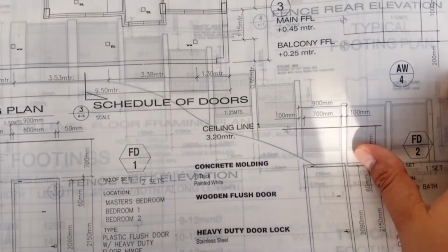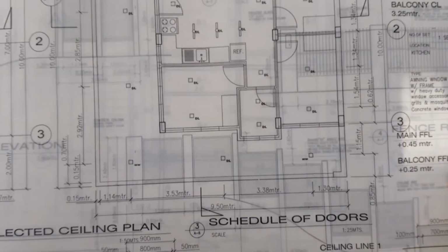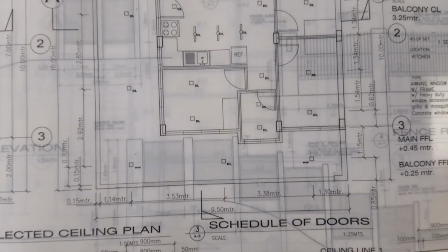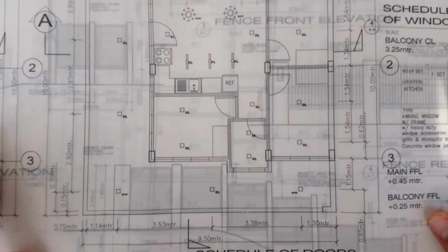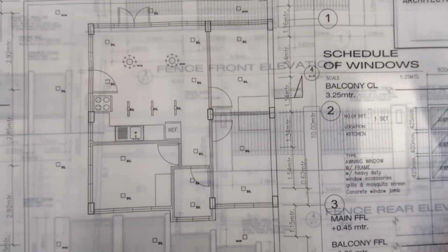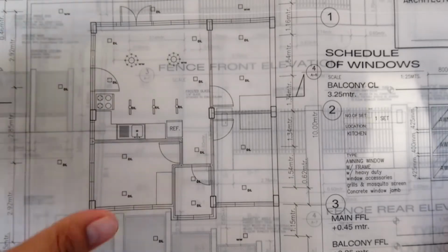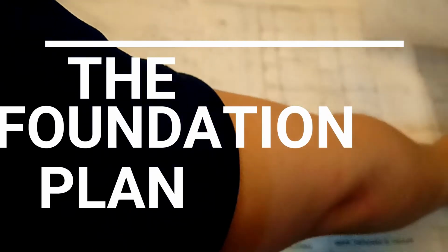I think our last assignment is for you to do the reflected ceiling plan. Okay, since we are in the pandemic and I can't check your work in person, I'll just show you how it should be done. Okay. Some of you did your reflected ceiling plans and you connected here the lighting, so that's wrong. So when you do your reflected ceiling plan, you just reflect the location of the lights and its lighting type, and also what's going to be the design of the ceiling. Okay, for this house, for example, it's just a flat ceiling with some pin lights here. Hope you can see this in the screen.